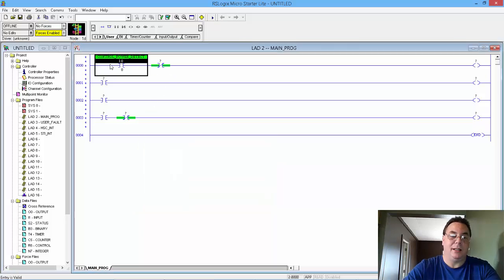And you can see that this contact has been assigned control power detected, input 0/0. Okay, so in other words, this will actuate and close, if you will, when your processor detects 24 volts DC live on the terminal input 0/0. And this, we're just going to leave that a closed contact for now and get programming that later.